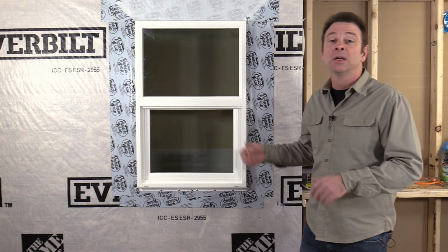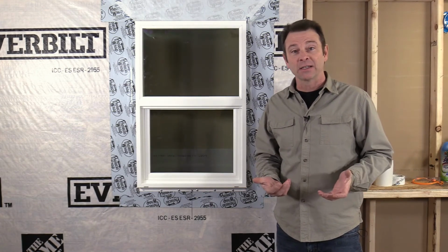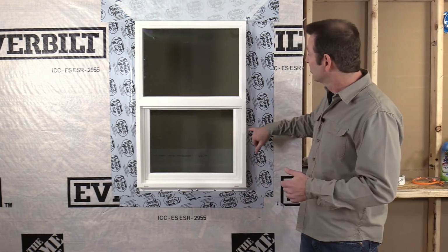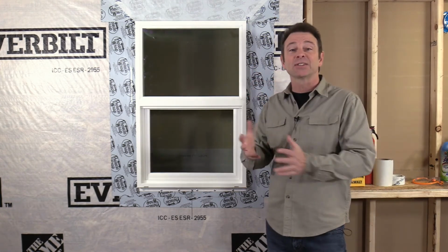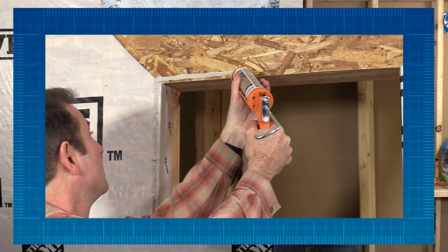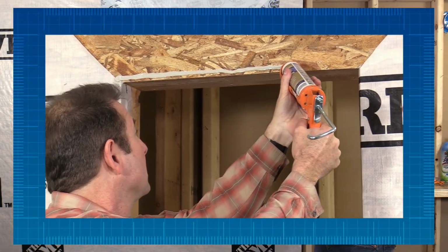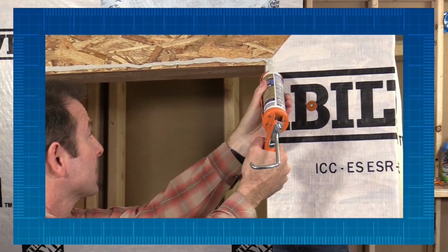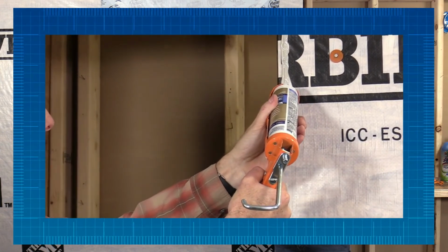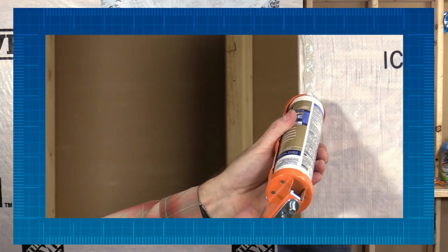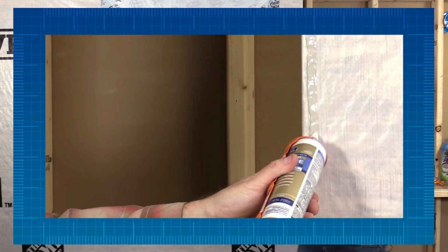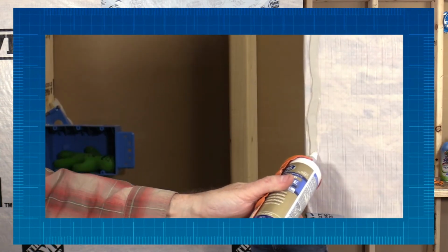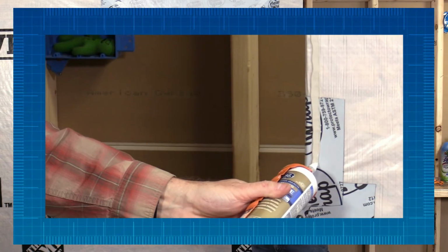We need to seal the window in place as we're setting it to the wall. We will do this with a silicone caulk, and that will be put on the flange or right on the rough opening. When those two meet, that's going to give us our first seal of that window flange to the wall. Placement of that caulk is really critical. The flange on this window is about 1 inch wide, so keep in mind that we've taken 1/4 inch away from that inch. We've got about 3/4 of an inch to hit with a solid bead of caulk all the way around, and so that caulk needs to be very precise, a nice solid bead.